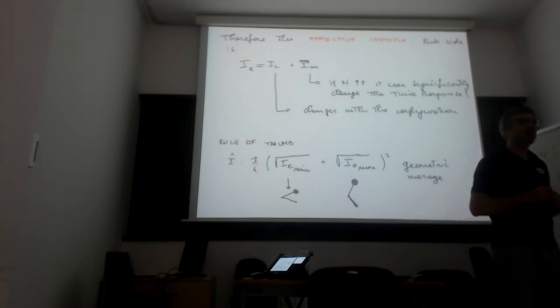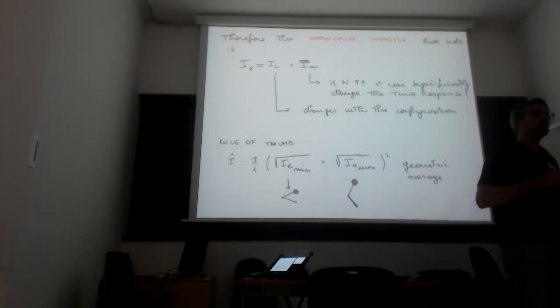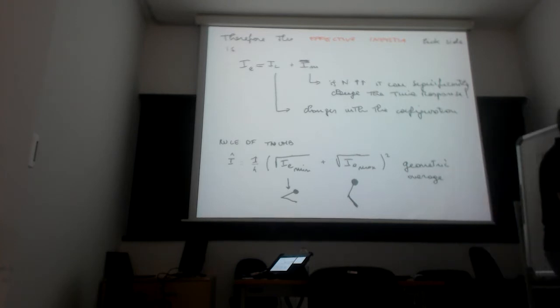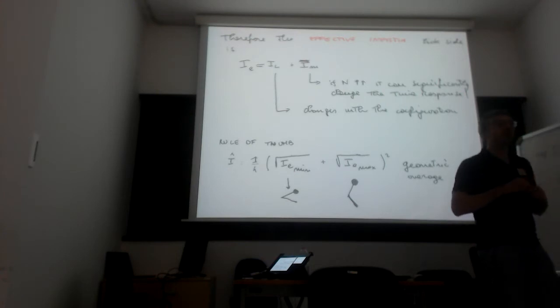If you apply this voltage, the current increases, and you have power losses due to Joule losses in the coils of the rotor. These Joule losses become heat, proportional to the square of the current, and will make the temperature of the coil increase until melting.